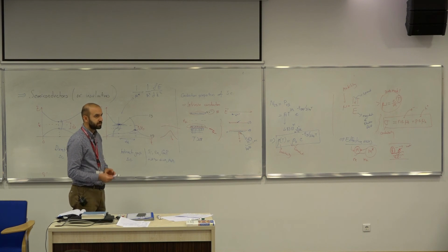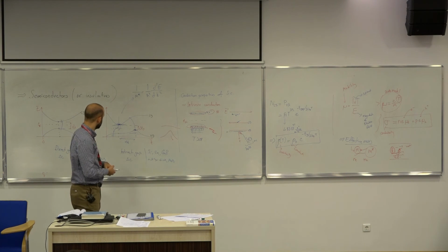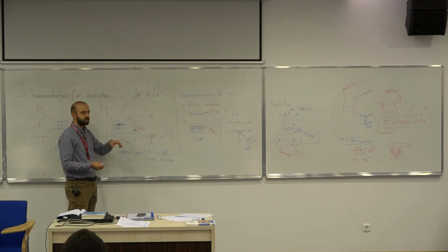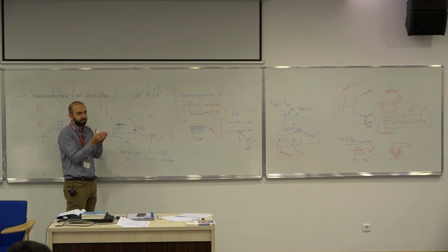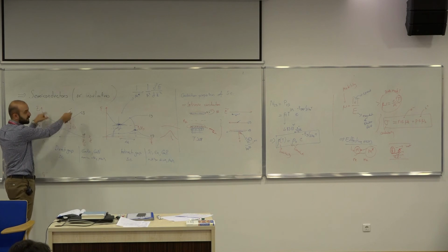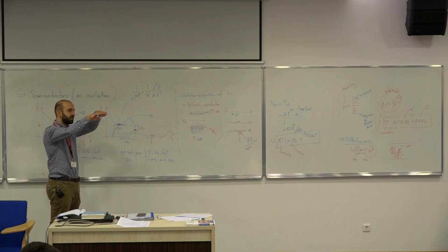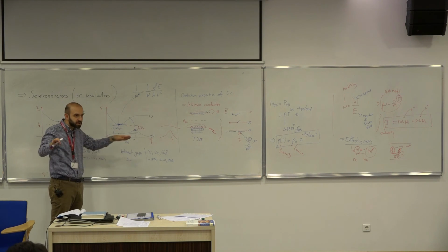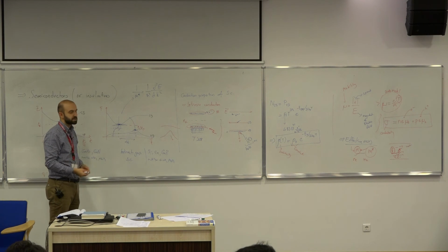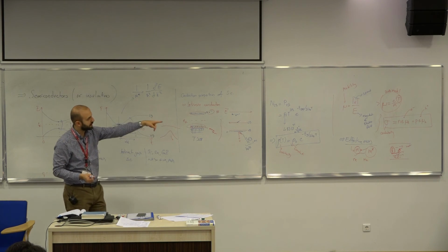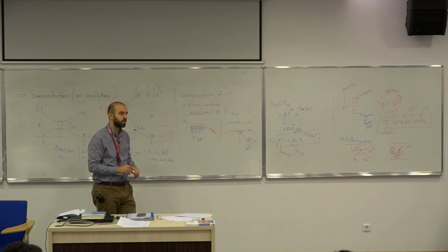Are the effective masses equal to each other? They're equal to each other, yes. And mu of e and mu of h, can they be different? They can be different. It completely depends on how the valence band and conduction band edges are curved. You can have a completely symmetric case, like I've drawn here. You can have a completely asymmetric case, very flat base of the conduction band and very sharp tip of the valence band. So you can end up with different effective masses.